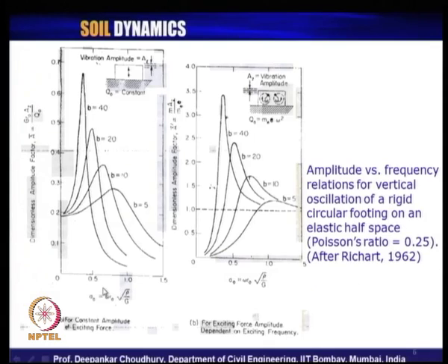So, A naught can be calculated, and B, mass ratio, also can be calculated. So, you go to this chart for constant force type vibration, vertical mode of vibration, and you can get these coefficients. Once you know G R naught by Q naught, you can calculate the vertical amplitude Az also. That is the use of this design chart, which takes care of F1 and F2.